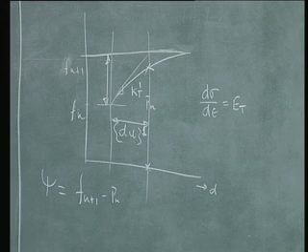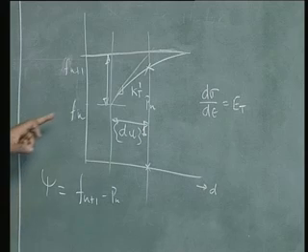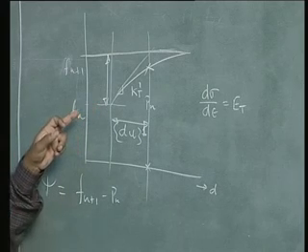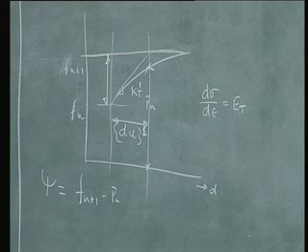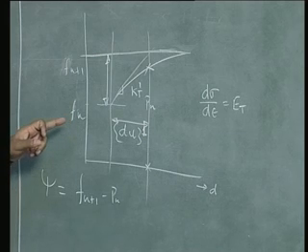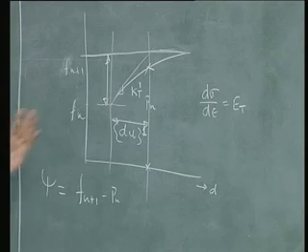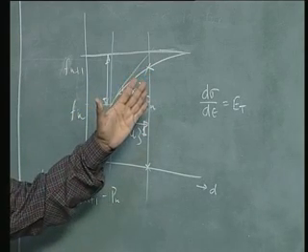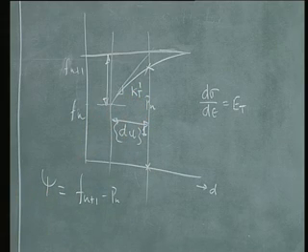So, yes. Last time we had the error is equal to load at n plus 1 iteration minus the internal force at the n plus 1 iteration. So, the question is, what is the error now? Last time we said that the error is to be calculated at the end of first iteration. I have not yet calculated the error now, okay. That is my next step.